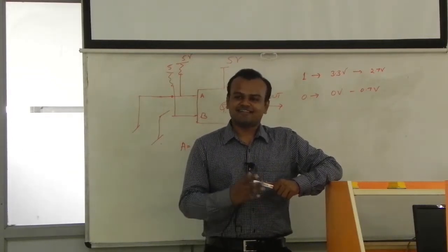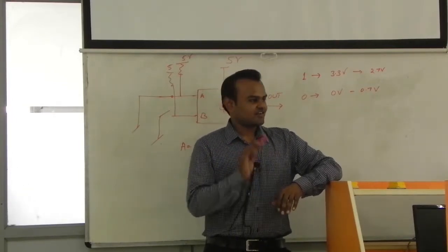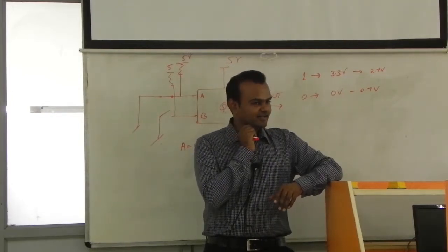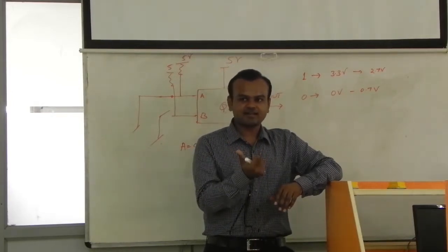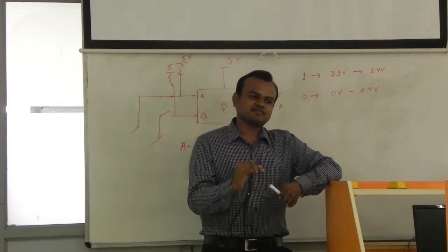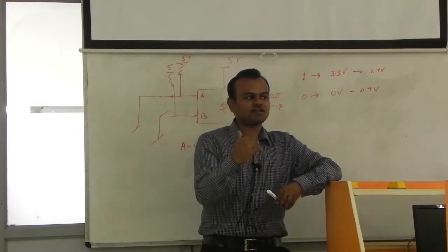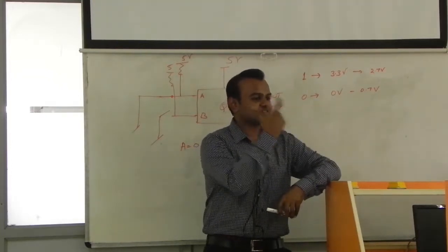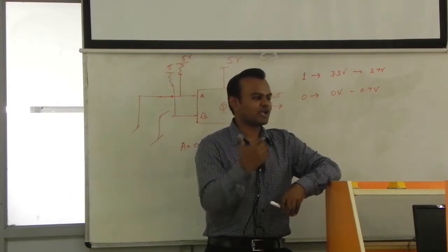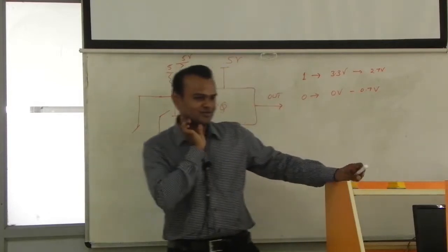Yeah, that's a complicated thing, but the basic thing is on UART there are particular baud rates, correct? 9600, 4800, something like this. To achieve that particular baud rate, the clock frequency has to be divided, right? So for that particular reason, that exact value 11.0592 is used. So it's not 12, it's 11.0592.